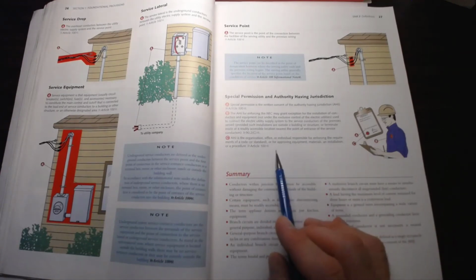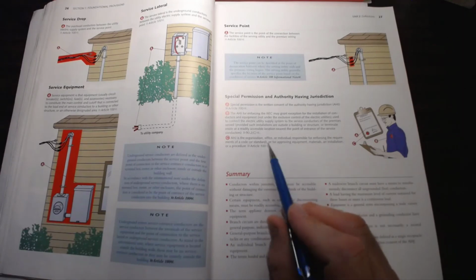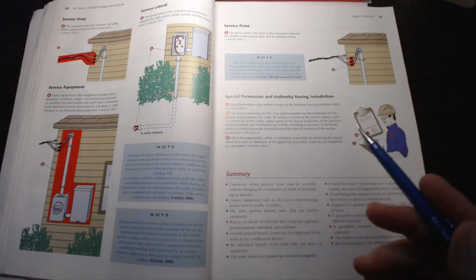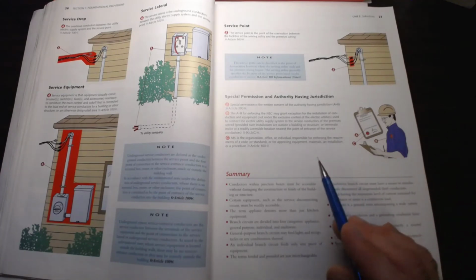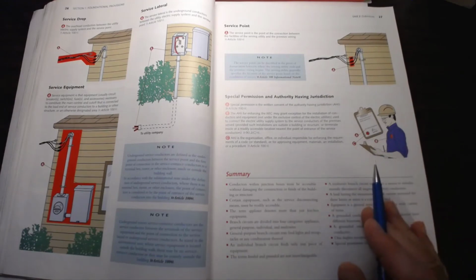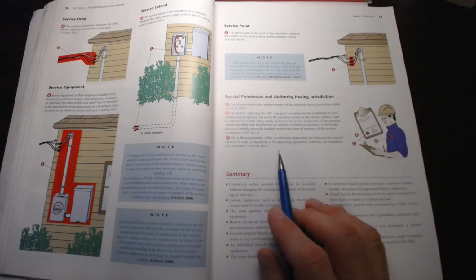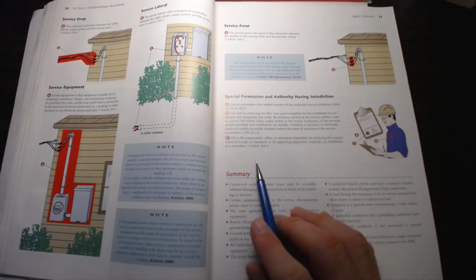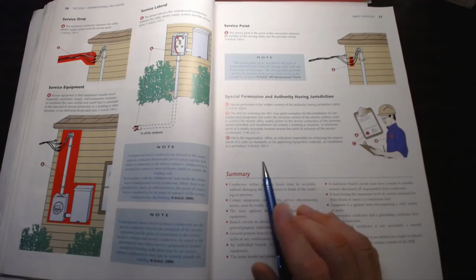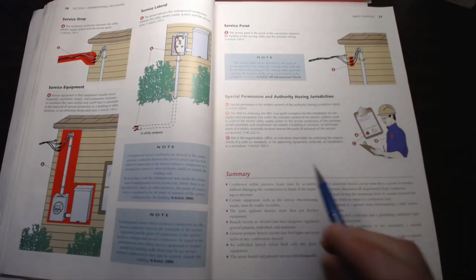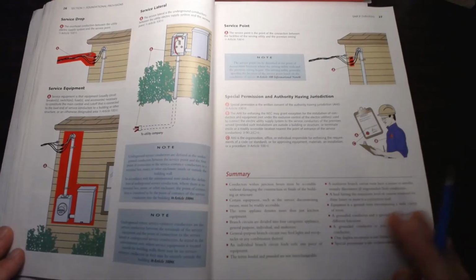It's also very important to know what that city or municipality or county wants, because you could have a location where they say you can only install galvanized rigid conduit on a rooftop. You cannot install any other type of conduit. I actually had that problem in Burbank. Burbank, I did not know was a GRC on rooftop only, where I had run EMT for quite a bit of the run. So that burned me right there, and it was a problem because I wasn't aware. I hadn't worked in Burbank that much. So it's always good to know and check what's going on in the city you're working in.